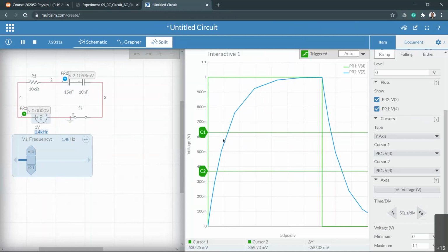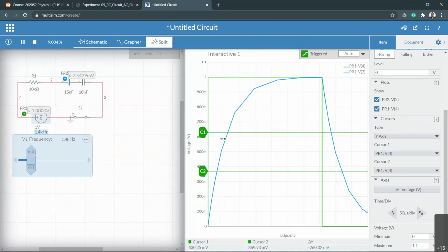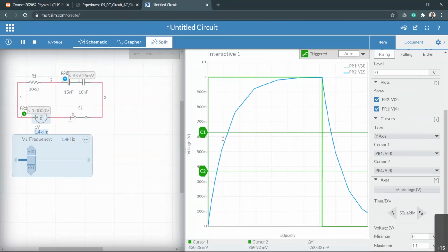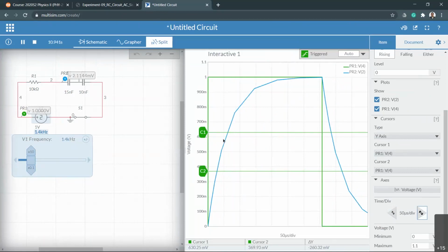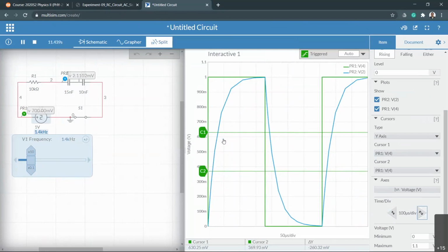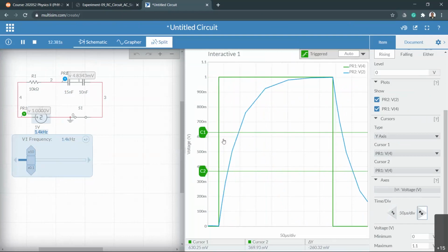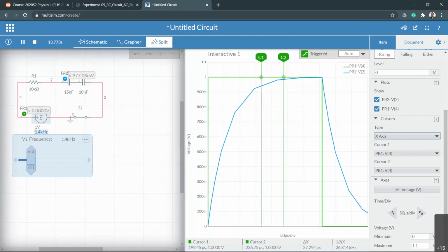Okay, now we need to measure 37%, thus 1/3 beyond the first segment for the charging curve. Then the discharging curve is actually just right here. Okay, you need to remember those places and then change the axis, cursor axis, and then measure them. That's all really. So x-axis, bring it here.